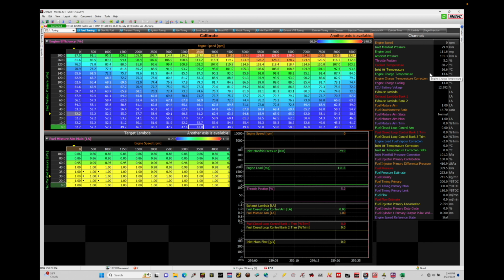It's going to go through some filtering. And what we find is if we have a skewed inlet air temp reading, our engine charge temperature is inaccurately calibrated. And we find that we have then an incorrect value calculated for engine load. So we need to understand how to deal with a heat-soaked intake air temp sensor reading. This is going to be a little bit more complex. I'm going to try to break this down and make this topic that's a little bit more advanced make sense, and how to deal with the variable of a heat-soaked inlet air temp sensor reading.